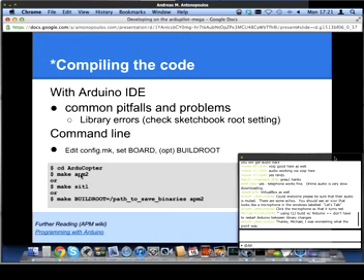What does the make CTL do again? Oh, CTL is the software in the loop configuration. Basically, instead of running, say, ArduCopter on the APM2 board, you can run ArduCopter on your computer, on your laptop, on Windows, Mac, or Linux in a simulated environment. And then you can use that to drive a simulator, to test the software with a ground control system, essentially do all of the flying you would do without any hardware at all, just all emulated in software. It's extremely useful for developing code.